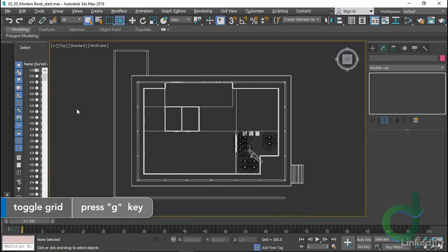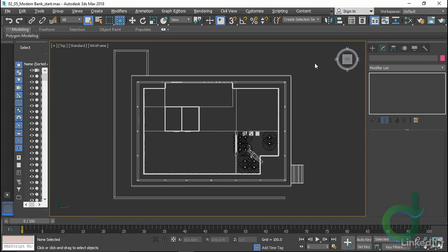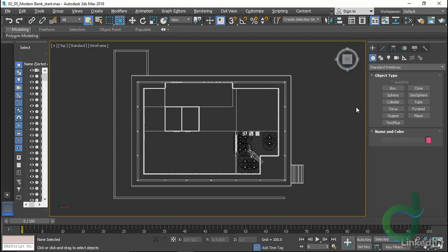There's a couple of ways we can do this. We can either start to make planes and sculpt them, or make one big object and sort of sculpt it into place, or start to do a flat mesh and use things like displacement maps and otherwise. What I'll do is create a series of planes and snap them together, as it's pretty easy, and then use some paint deformation to give them a little bit of wave. I'll hit Create and choose Plane.